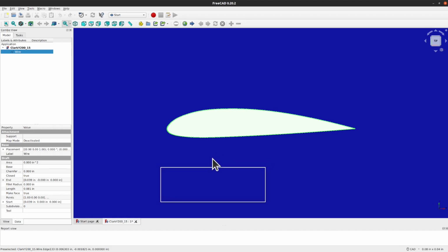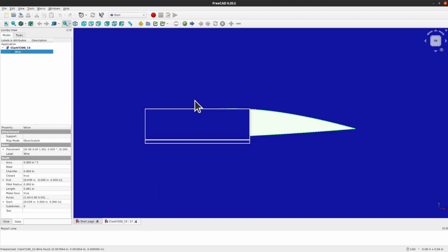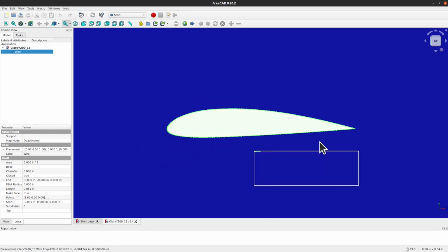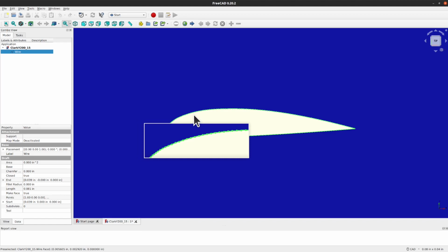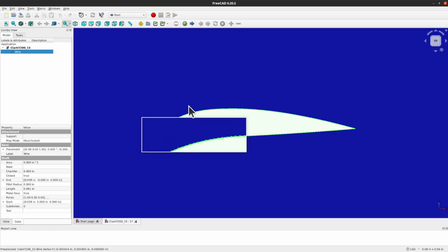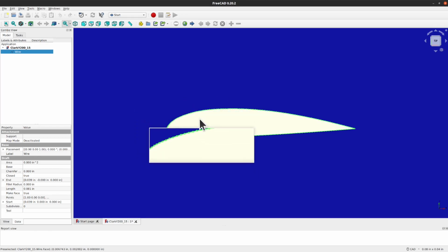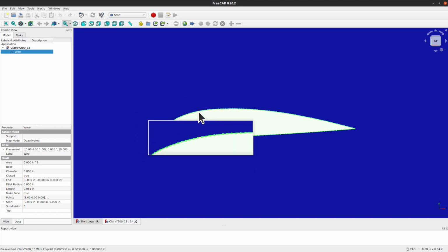Now, I mentioned before you might want to do offsets. For example, I'm building an aluminum airplane, or at least designing an airplane right now that's aluminum. And I've got 16 thousandths thick aluminum sheet that goes all the way around the wing. And then I have ribs that have flanges on them that rivet to that sheet. That's 20 thousandths thick. Now, if I want to make a form block for my aluminum to bend over those flanges, I'm going to have to make that form block smaller than the skin thickness and that flange thickness. So adding those two together, that's 36 thousandths.